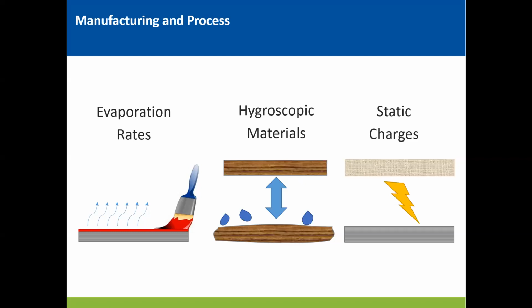Static electricity is a final concern, and this is certainly something here in Canada you'd be familiar with in the wintertime, even just walking around your house or getting out of bed in the morning, the shower of sparks that come off the bed sheets. And really what's happening here is when the relative humidity is higher, the moisture molecules in the air are providing a path for electricity to dissipate through the air.